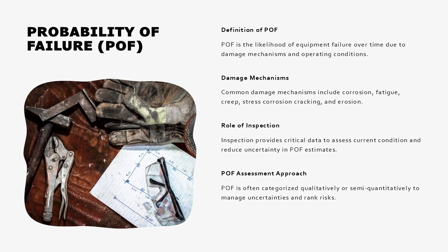This approach reflects the inherent uncertainties in degradation modeling and supports consistent risk ranking across large populations of equipment. Understanding POF enables engineers to predict how risk may change over time and to plan inspection intervals accordingly.